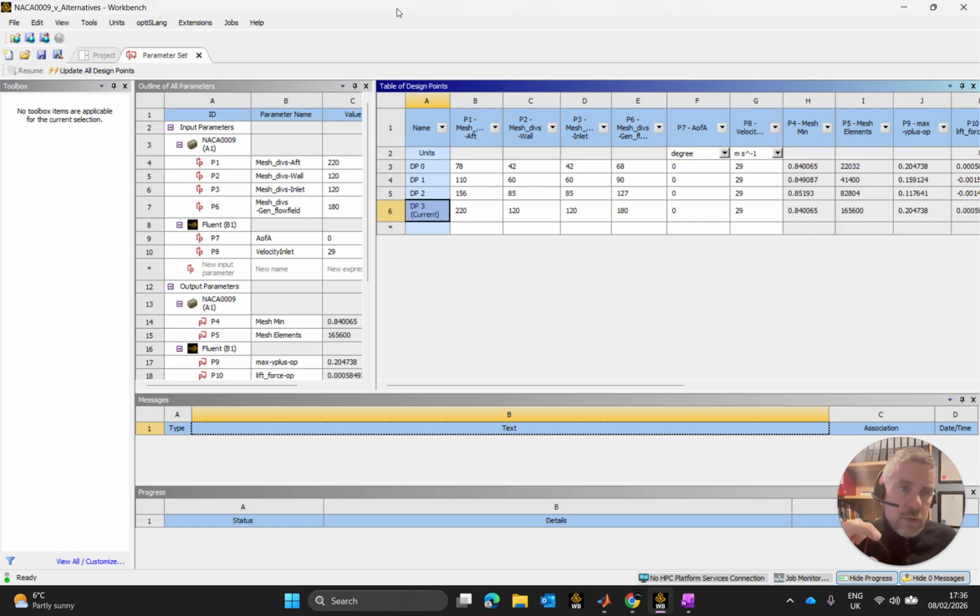So again, even though OneDrive syncs into the C drive, you should do your ANSYS Fluent evaluations on a non-syncing C drive, even if you select to keep the files on the computer all the time as part of your OneDrive management.